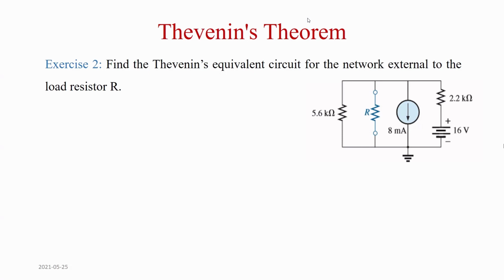Okay. So Thevenin theorem, which says any two-terminal linear network. So if you have a network that has two terminals, usually those two terminals, we connect a load between them. We can find an equivalent circuit, a circuit that will do the same job. This equivalent circuit is only one source and a resistor connected in series with that source, and the source is a voltage source.